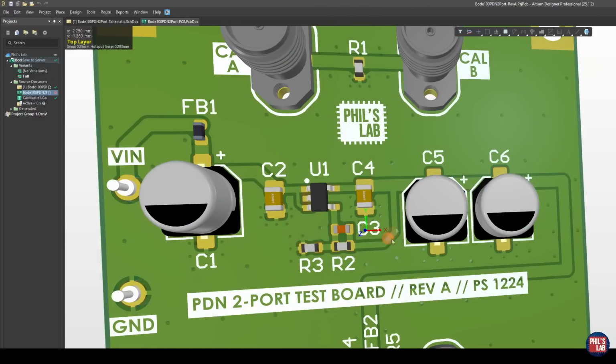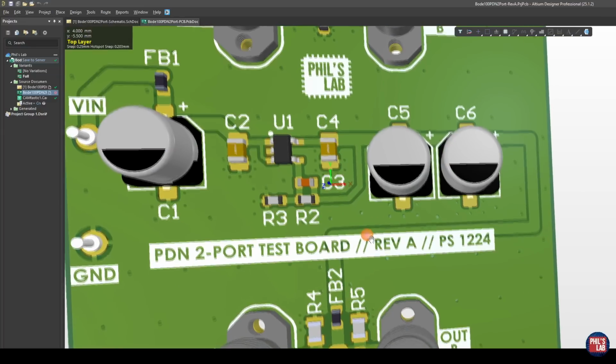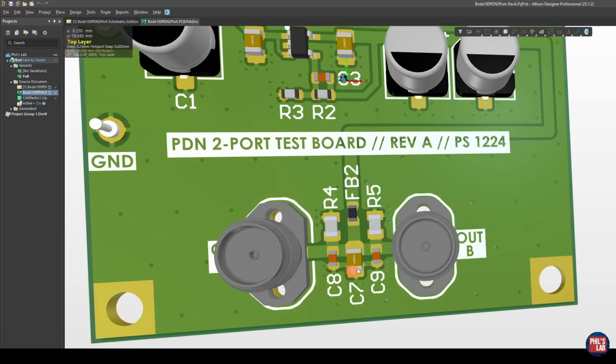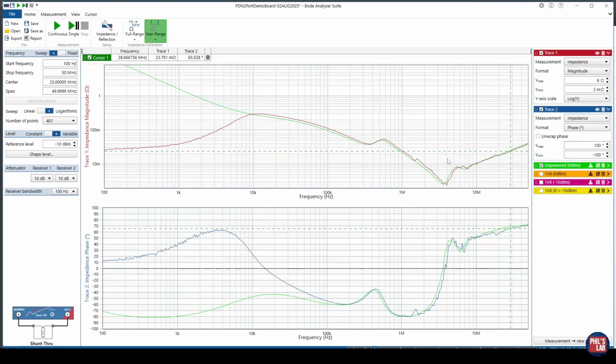Again, the low frequency region, when the board is on, is dominated by the control loop of our regulator, or VRM. Then the low frequency region is also dominated by C5, C6, our bulk decoupling capacitors. As we move higher in frequency, C3 and C7, because they're smaller packages, lower ESL, lower ESR, will dominate the impedance profile until we reach the ESL region, where the inductance of all of these parts dominates and our decoupling performance worsens. So overall, performing a quite simple measurement, as long as of course you have the gear to do so and the access points on your PCBs, you can extract the PDN profile at a specific point of load quite directly.